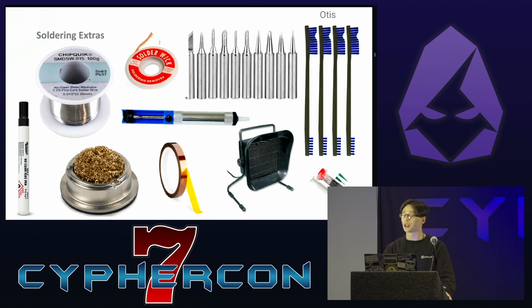It can also be helpful to get a couple different tips for your iron, experiment, see which ones you like, see which ones you can get good thermal contact with. I like the ones that are kind of shaped like a rounded-off flathead screwdriver. I find that I can usually get pretty good results with those, but sometimes you want a really fine cone like the one all the way to the right. That can help with some of the really fine, tiny pins.